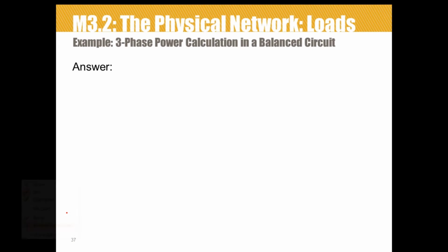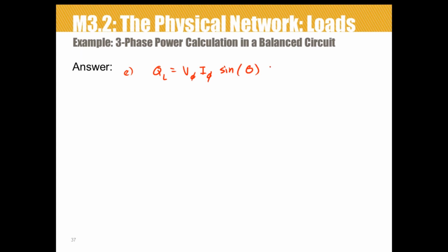Just make some space on the slide. Part E asked us to determine the total VARs absorbed by the load. So that's asking us to calculate the reactive power in each phase of the load. Remember, the Q in the load is just the magnitude of the phase voltage times the magnitude of the phase current times the sine of theta. We already performed all this math before, so it's 115.22 times 2.4 times the sine of 35.68.